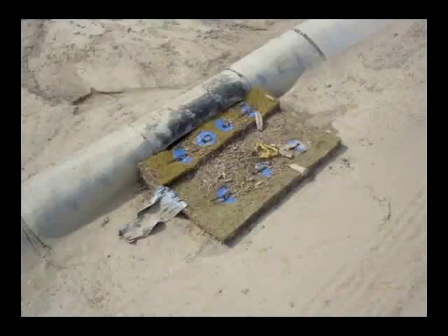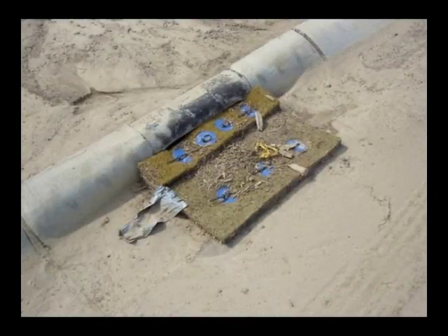In contrast to placing the fabric under the grate, filter fabric and filter mats may be placed on top of the grate and over the curb cut on street drains to filter small quantities of sediment. These controls require constant maintenance. The fabric must be replaced and the mat cleaned after every runoff event. The above controls should never be used on flat, low-profile grates or yard drains.